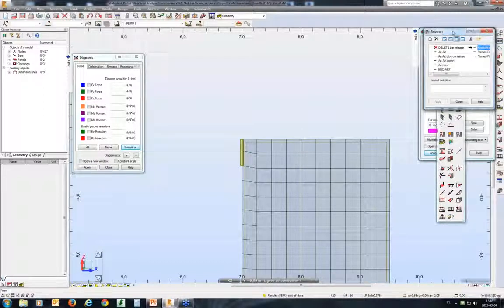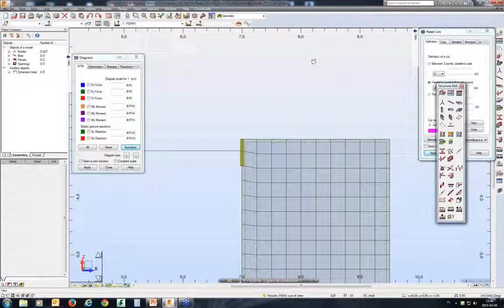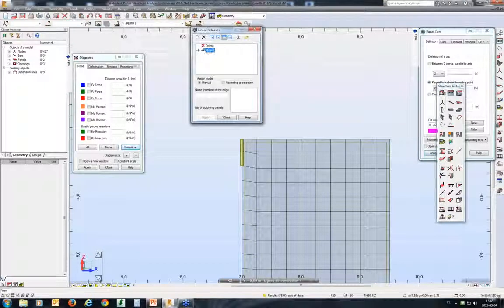And if you want to do the same for a panel, for example, you use a vertical panel standing for wall and a horizontal one for beam, there is the option for applying linear releases on the edges of the panel, and this is the way to tell the program that the connection between a wall and a slab is pinned, no bending moment transfer. By default, there is a bending moment transfer, with the exception of the solid, where you don't have rotational degrees of freedom. But this is an entirely different story, and I don't think that many of you are going to work with solids in Robot.